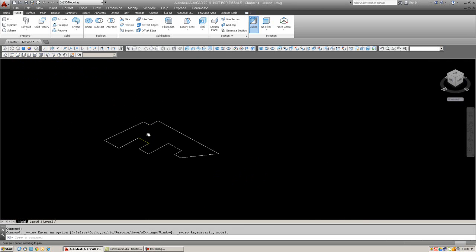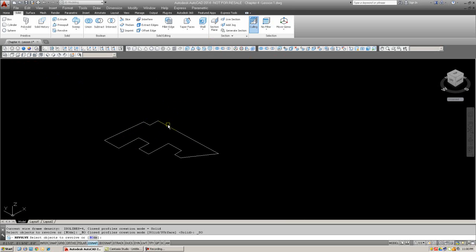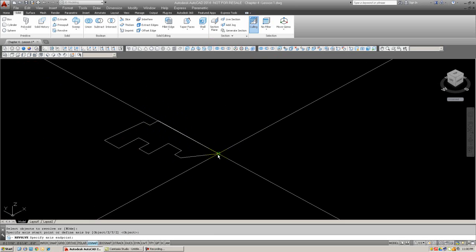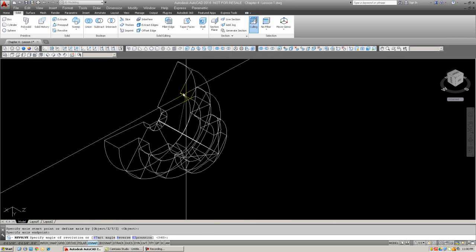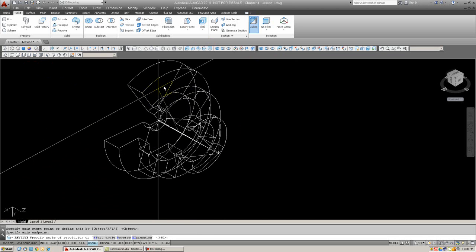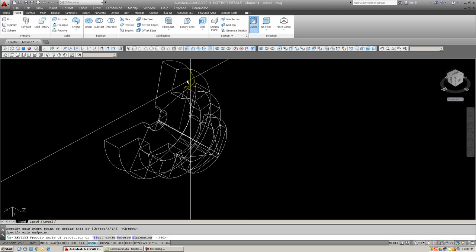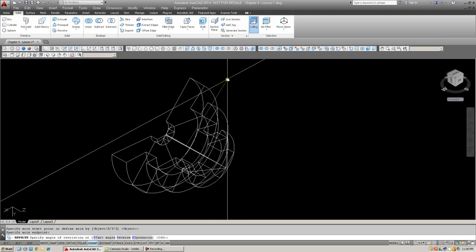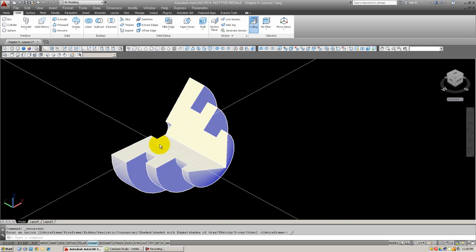And for dynamic, I'll go into 3D, do the revolve command again, and specify the axis. And as you can see, you can do this dynamically. Like many other commands, you see a kind of a pattern here. AutoCAD allows you to do this. And sometimes you may want to do this if it's a random cross section. And you can just click when you're done and shade it. So that is a random positioning.